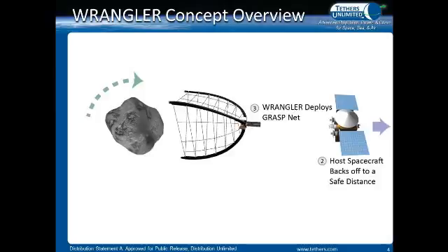That deploys out using inflatable booms, deploys a net out. We chose a net because it's just easier to see what's going on, and for the initial applications where we were just trying to grab onto spacecraft, it worked fine. The main reasons for going that route were that a net compacts much smaller, and we were looking at using very small, CubeSat-scale spacecraft to grab onto very large spacecraft. Though we looked at using a bag or something of that nature to capture debris, it just doesn't pack as well as a net, which can have a very sparse, low density construction.